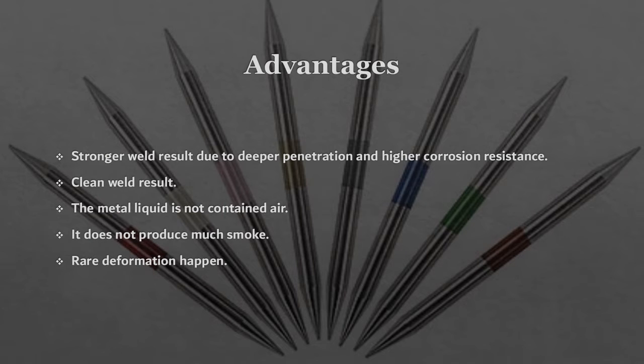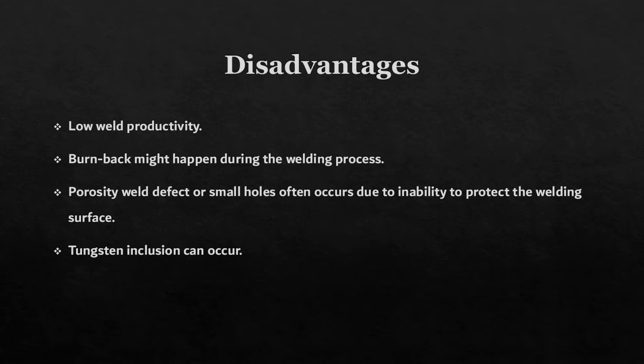The advantage of this process is that it can produce a stronger weld result due to deeper penetration and higher corrosion resistance. The second one, it can produce a clean weld result. And the third one is that the liquid metal does not contain air. The fourth one is that it does not produce much smoke. And the fifth one is that rare deformation happens. However, the disadvantage of this process is that it has low weld productivity.